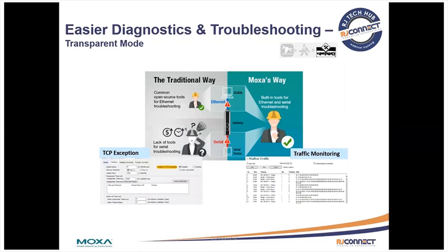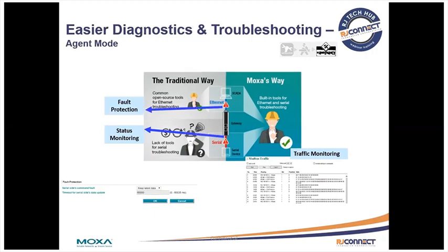So with transparent mode, continuing on, this is for diagnosis. Moxa has built-in tools for Ethernet and serial troubleshooting. It can be very difficult to troubleshoot serial-based communications when using Modbus RTU, and Moxa's gateways make it easier to implement monitoring tools such as the Modbus traffic monitoring tool and TCP exception in the gateway setup itself.